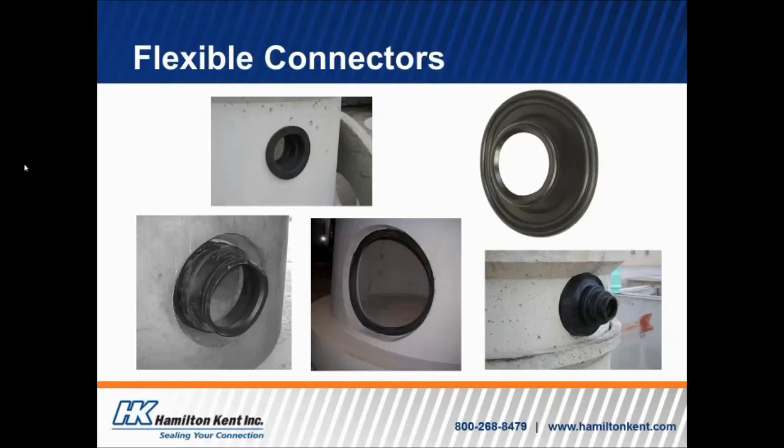There are different types of requirements that jobs have, and so there are different abilities that these gaskets or connectors have. Some of them will offer more deflection than others. Maybe they'll offer 5, 6, 7 degrees of deflection of the pipe coming in. Some will have greater strength in what they're able to withstand as far as water tightness. Your typical connector is going to be 13 psi, but there are some that are meant more for a soil tight type connection, and those will be a 6 psi connector.